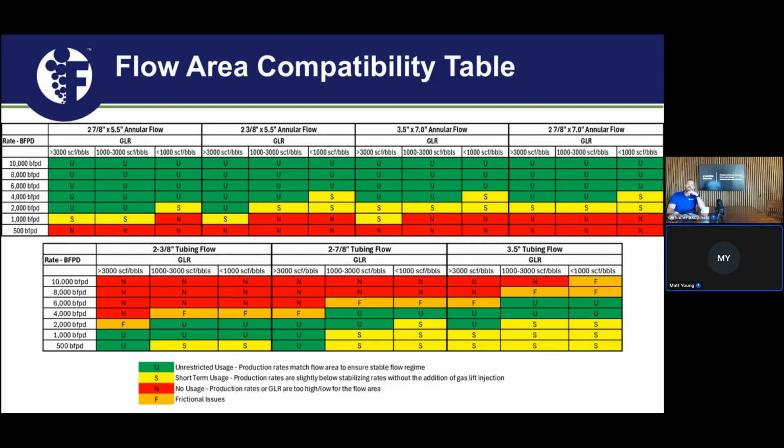So one of the big things that I take away from that conversion zone, there's really three primary ways to identify that. Look for that instability or heading of the well and make that decision then. Pick a production rate based off of historical production and make that conversion then, or run that instability calculation or model through a hydraulic nodal analysis program to understand when that conversion is going to be.